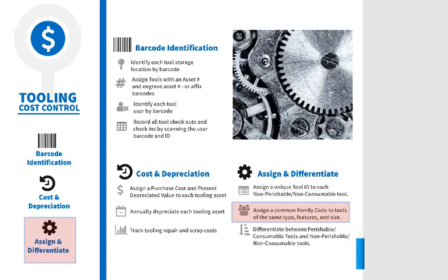Let's say you have 10 tools of the same functionality and size. Now, you don't want to overuse one and have the other 9 sitting in inventory not being used, because that will tend to cause end product defects. So you want to be able to circulate these tools, and also you want to make sure you don't have too many or too few of them available. If you have too many, that will increase inventory costs, and if you have too few, it causes bottlenecks on the shop floor because the tools aren't available when they're needed.